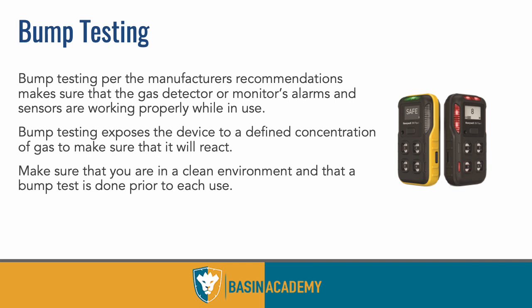And these monitors fail a lot, right? Leaving them out in the cold, dropping them, leaving them out in the heat. A lot of things can affect the sensor and change what it's reading, which is what we call calibration drift or sensor drift. And it's going to change from, maybe it starts reading at 12, right? Or 14 or 20 instead of 10, or maybe even less. Maybe it starts reading at 5 when it should be reading at 10. It can drift either way, but that's why a bump test is important.